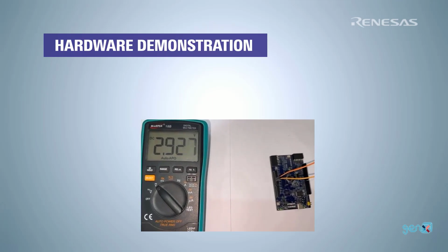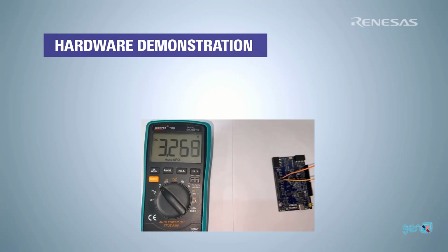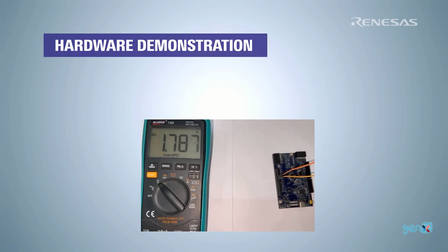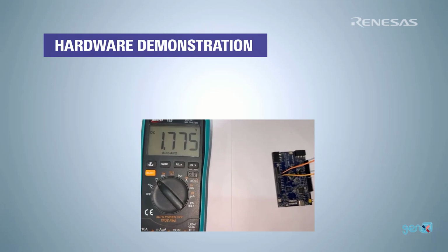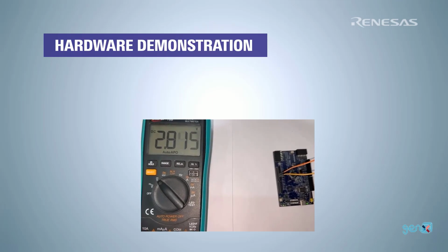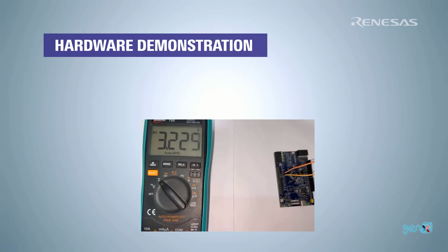When I gradually increase the voltage, the LED status flag will be set, and in the while one loop we will turn on LED 2 as we can observe in this video. And if we gradually reduce the voltage value below the OFS register threshold value, a brownout will be detected and the board will be completely shut down. If we gradually increase the voltage, first the low voltage interrupt will be generated and both the LEDs will turn on. After that, if we further increase the voltage, LED 2 will be turned on indicating the normal mode.